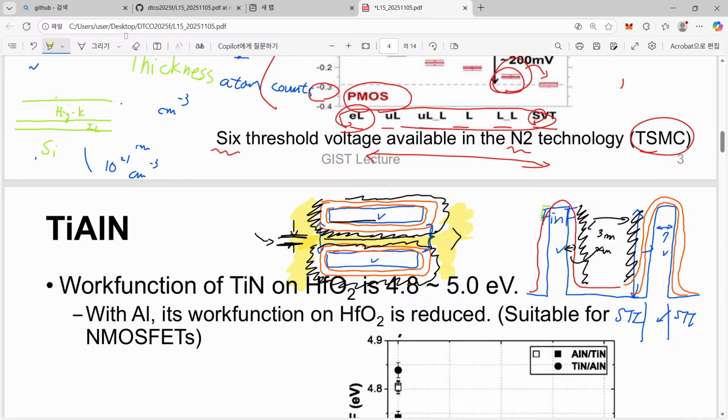So it is not that good for its conductance. So we need a really good metal. Pure metal is required. However, if we have this short distance, it is almost impossible for us to fill this very narrow slit with our bulk metal. Then what will happen? There is no gate at all. So it is related to the failure of your device. You cannot turn on and turn off your device effectively when you make this fault in your device.